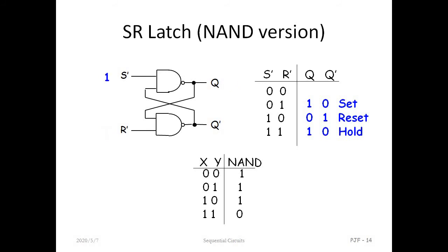Next is 1 1. Similarly 0 0. Whatever the input, with 0 0 the output is always high. So Q is 1, Q bar is 1, and 1 1 becomes 1. So this is not defined, because we cannot store. This is called the disallowed case.